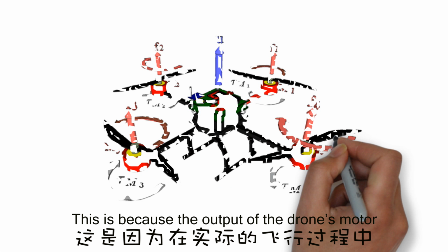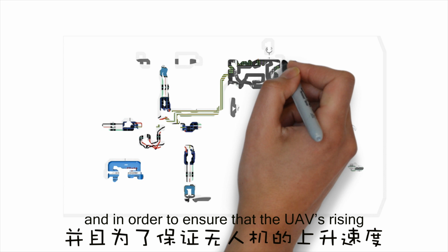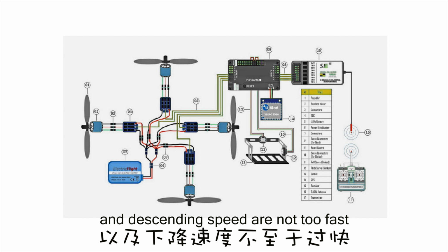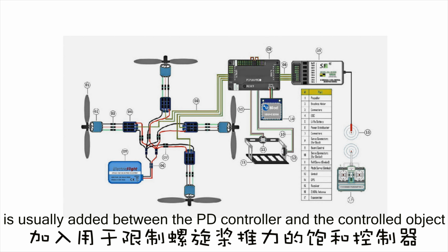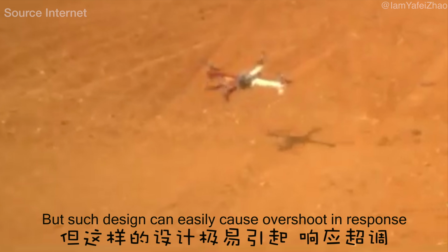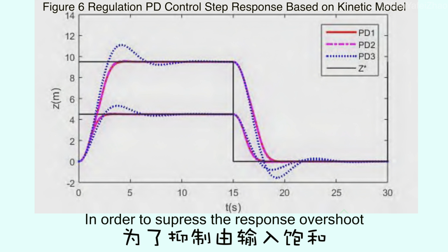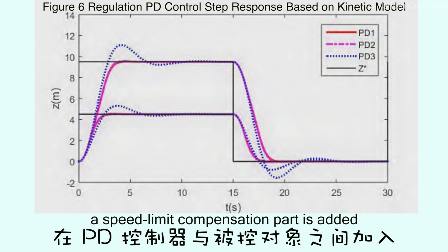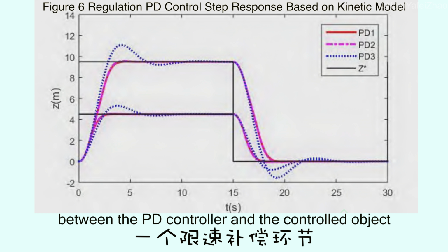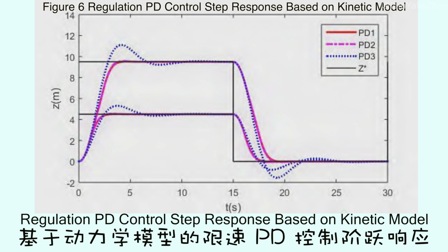This is because the output of the drone's motor can be limited during actual flight, and in order to ensure that the UAV's rising and descending speeds are not too fast, a saturated controller that limits propeller thrust is usually added between the PD controller and the controlled object. But such a design can easily cause overshoot in response and reduce system stability. In order to suppress the response overshoot caused by input saturation, a speed limit compensation part is added between the PD controller and the controlled object. At this point, the simulation results are shown in figure 6, the regulation PD control step response based on the kinetic model.